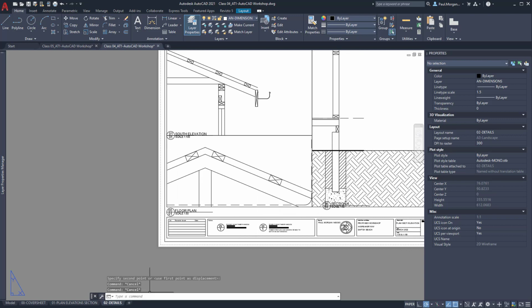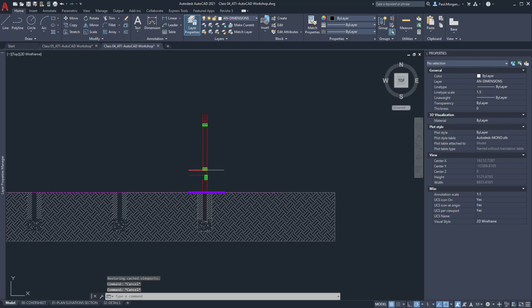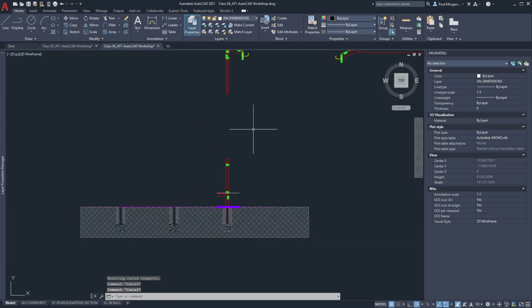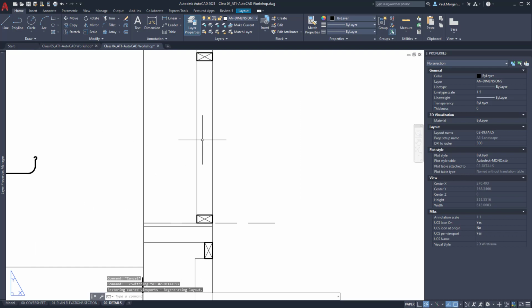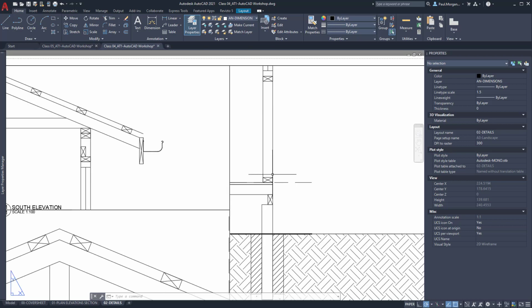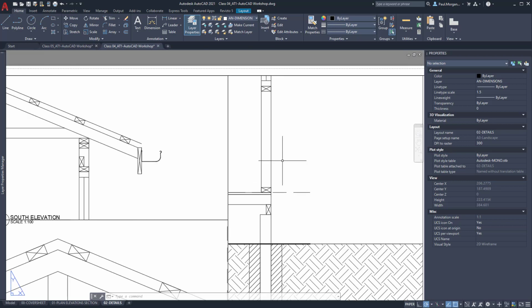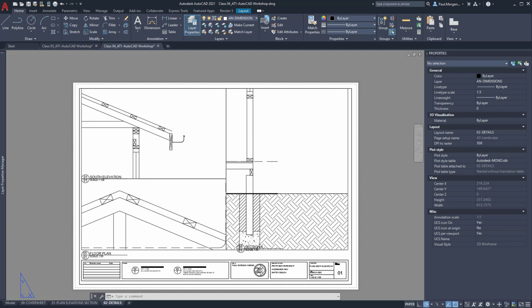Okay, cool. Now, back to CAD. So at this point, two things you need to remember. One is that you need to uplift the line weights when going to details, because the drawings are getting bigger, so each of the line weights will no longer work. If I go back to the details and zoom in, you can still see the line weights of, say, the stud versus the stud section versus stud projection, but it's nowhere near as definitive as it was prior on a much smaller drawing, in fact a drawing 5 times smaller.